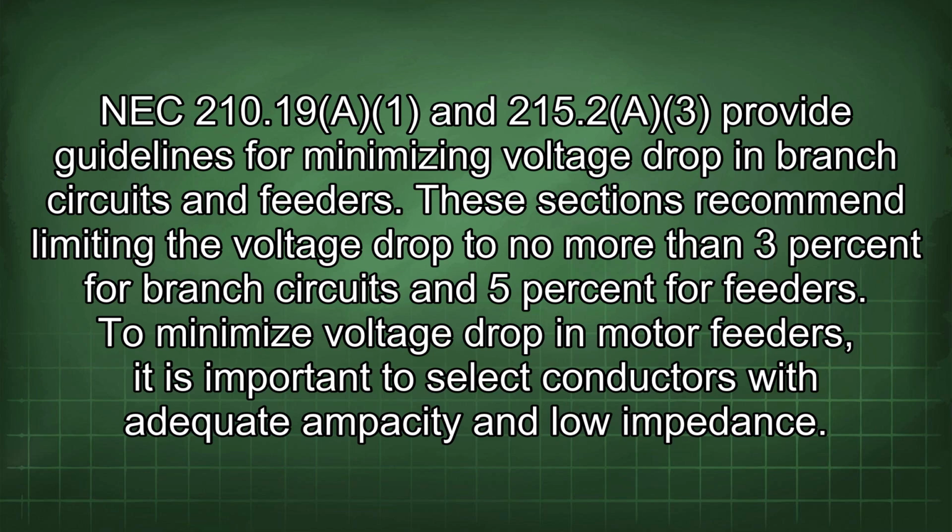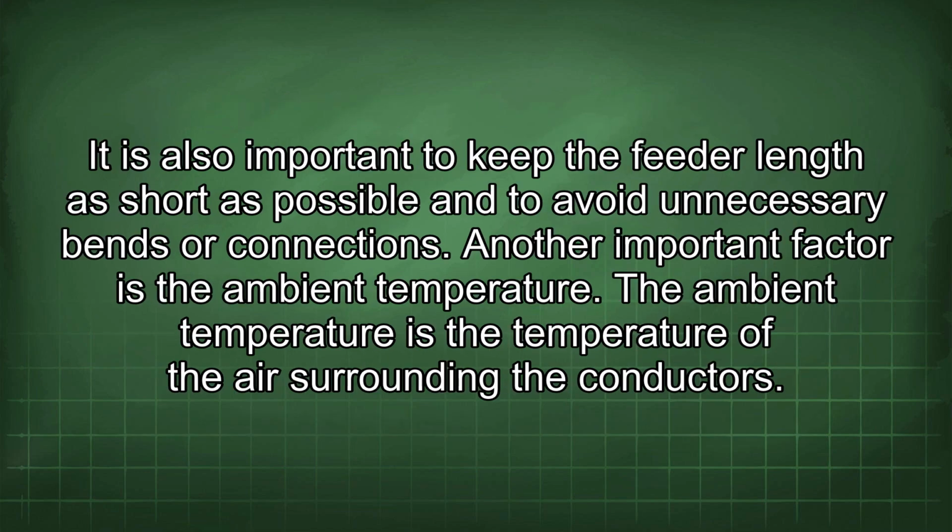To minimize voltage drop in motor feeders, it is important to select conductors with adequate ampacity and low impedance. It is also important to keep the feeder length as short as possible and to avoid unnecessary bends or connections.